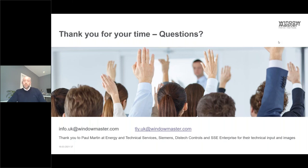The logic that we've got built into MV Embedded is multi-layered, it's quite sophisticated, and it's been proven. And so that's what we lean on typically. It's got lots of different factors that we can set within it, so for things like purge ventilation, trickle ventilation, setting limits for security, nighttime cooling regimes, things like that. It offers an awful lot of flexibility as it is. If there is a specific requirement for a project, then I'm sure we could probably look at it, but we need to understand exactly what that is.